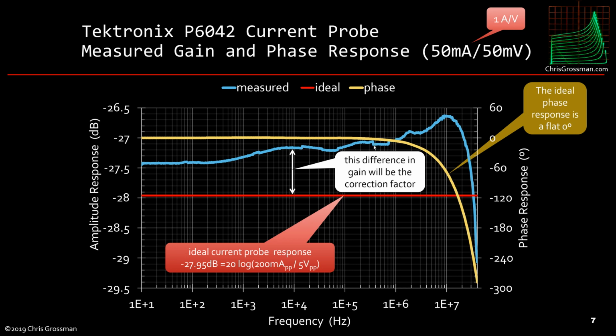Now these jumps look big, but that's just because of the scale. If we look over here at the scale, each division here is 1/10 of a dB, and the biggest jump is less than that. Most of them are around 0.05 dB. And those are small, so these errors, although they look big on this scale, are pretty tiny. The scope's doing a good job. And these small errors, if you were looking at a waveform in a scope, you would never notice. The only reason we're seeing it is because we're looking at very fine detail in this gain response.